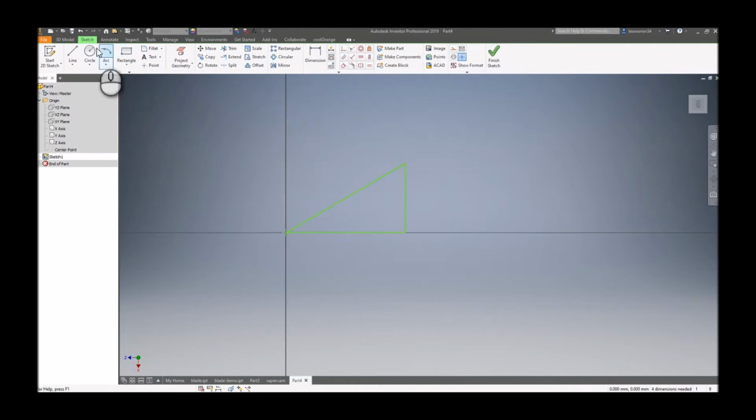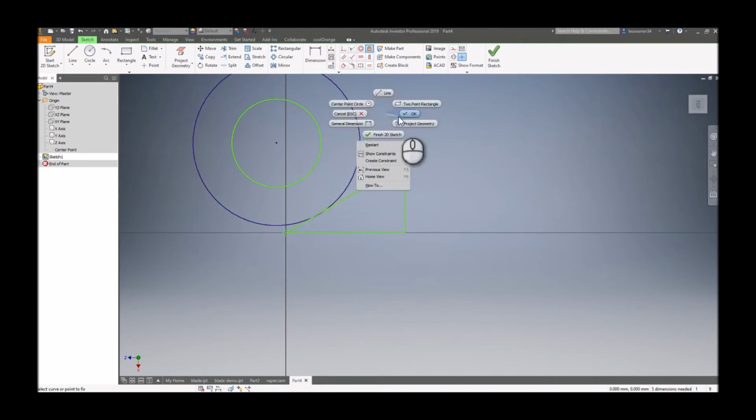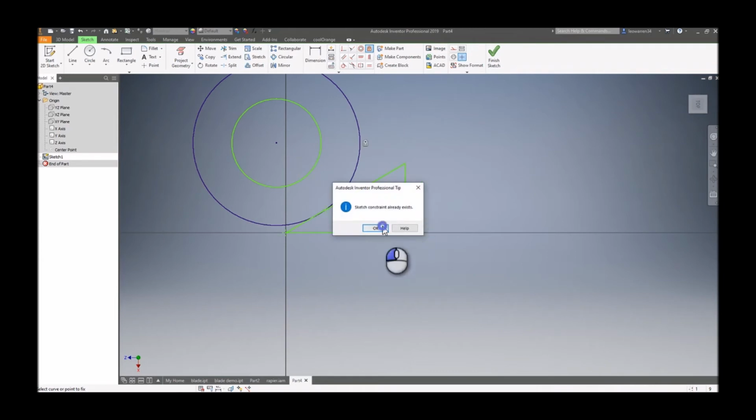coincidence, so let's say it's got 2 circles, so it's got a circle here, and if I put a point down, there you are, it's now also a special tangent point. Then there's concentric, so if I just make a circle there, make it concentric to there, it's now concentric. This is just like an override, so whatever you select, it will lock it regardless of whether it's properly constrained. Not the best habits because it doesn't always constrain it in a way that you want. So yeah, we can now remove that.